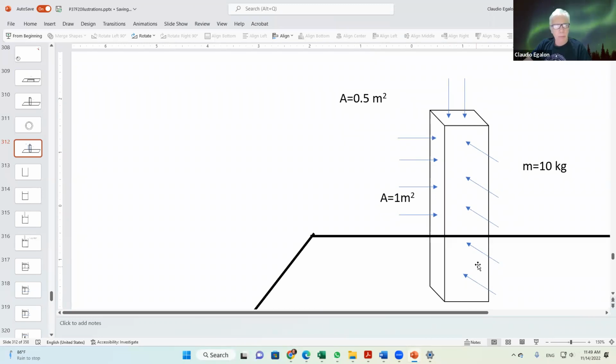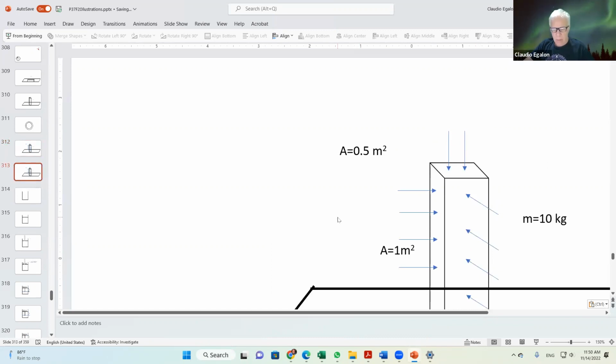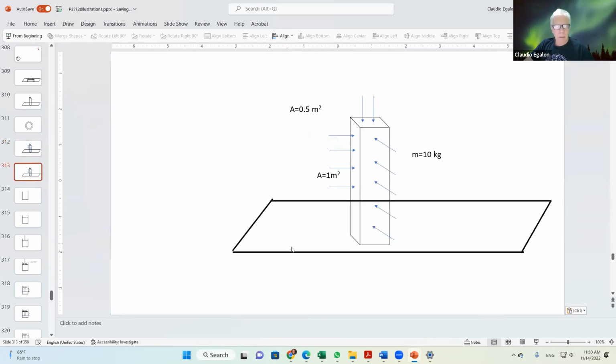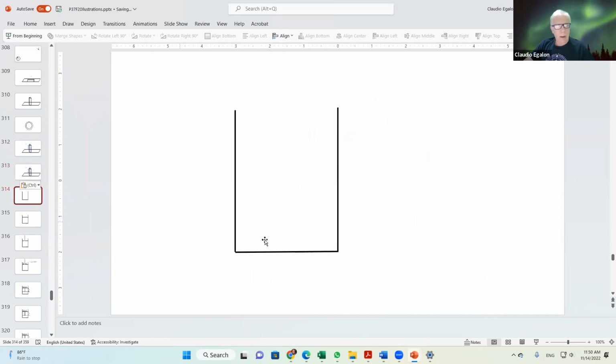And that's where we come to talk about pressure due to a submerged object. Let's talk about that. Here's my container, my vessel, that I fill with water. Don't forget that at the surface of the water, you have this column of air exerting a pressure of 1 atmosphere, or 100,000 pascal, 101,325 pascal.